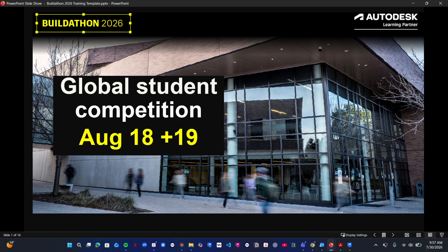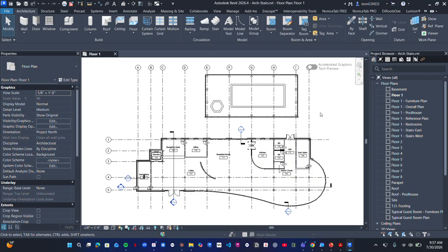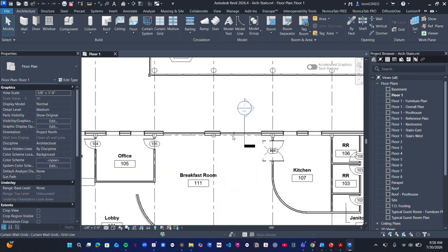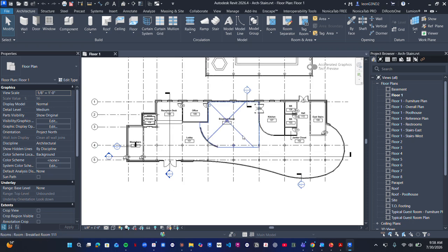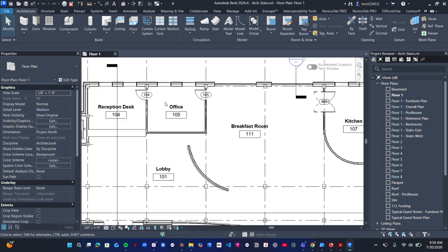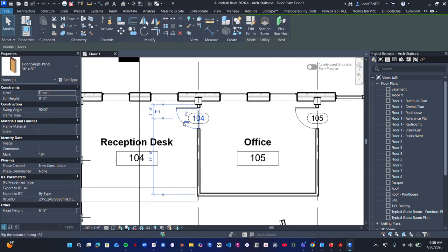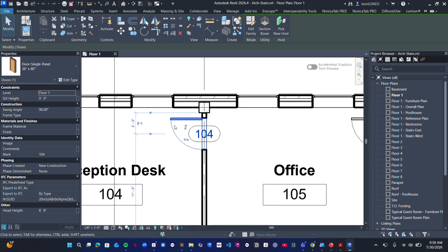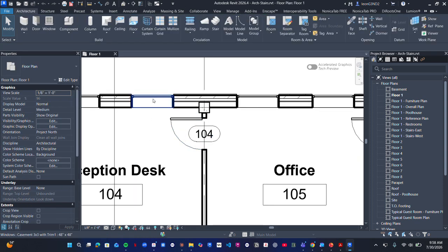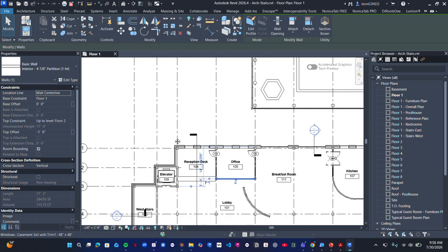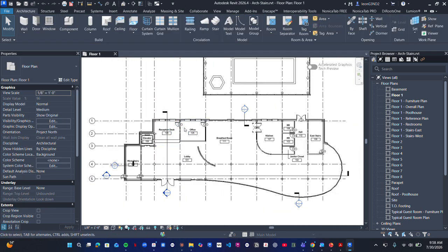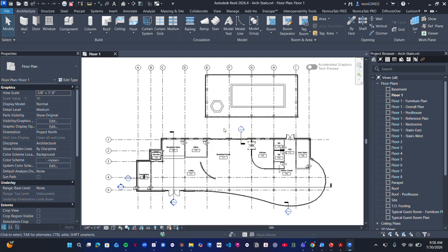Just to keep in mind, as I had said before, everything we have placed inside of Revit is essentially a family. That includes the windows, the doors, and the furniture. These are all considered family types. And every family was built inside something called a family editor. So these are built-in families, or hosted families, my apologies. Doors and windows can be considered hosted families, and then walls are built in, such as also floors that are actually families that inherently come inside of Revit.